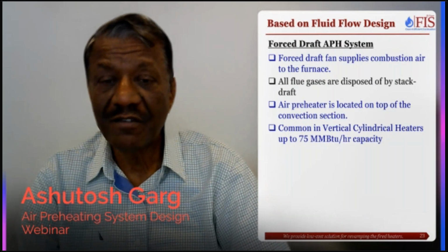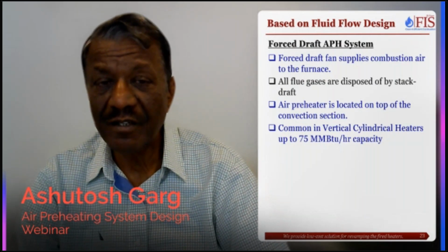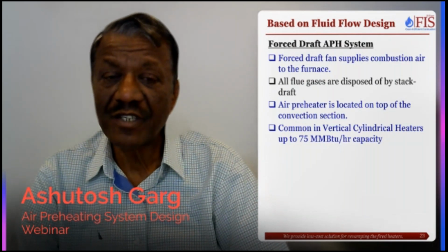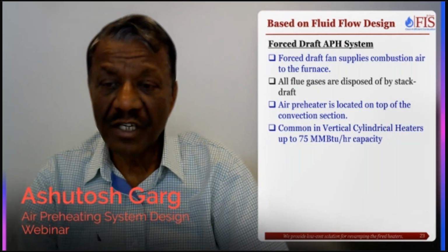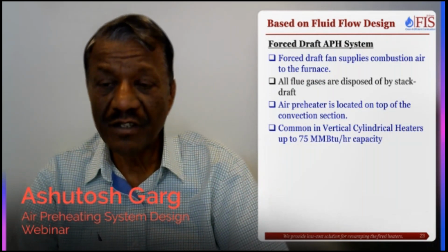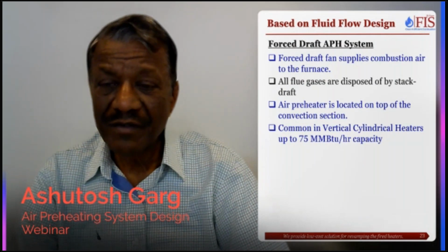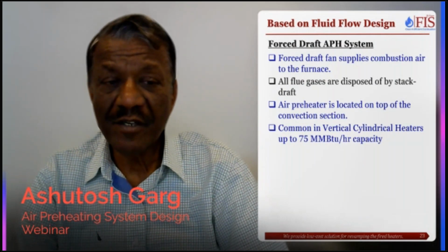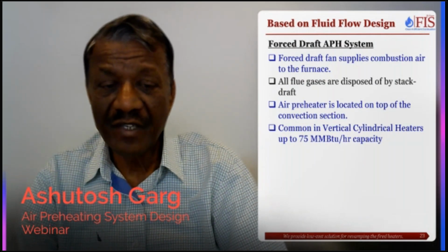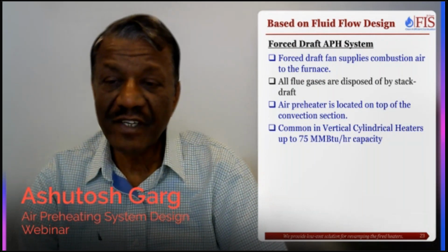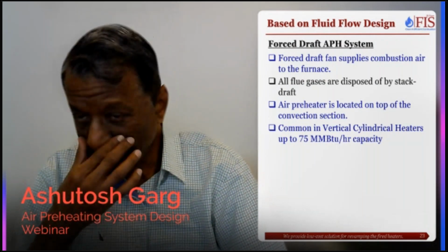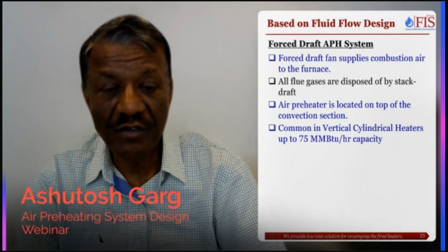But when you have a tubular air preheater and you're using the stack to generate the draft, you have a restriction on how low you can go down in the flue gas temperature. We have seen a number of tubular air preheaters, especially in India, where they have used this concept for up to about 15 or 20 million kilocalories, mostly for small heaters, but you can go even for bigger heaters.